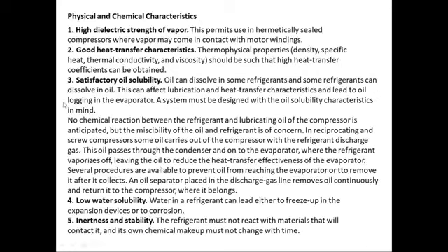So moving on, the physical and chemical characteristics. Number one, it should have a high dielectric strength of vapor, because your refrigerant, after circulating from the evaporator, goes into the condenser and into the compressor, and the normal compressor that we are using is a hermetic type compressor, where the motor is inside the compressor. It is not outside the compressor. The lubricating oil is also in the same sump, and refrigerant in vapor form will also enter the same casing.